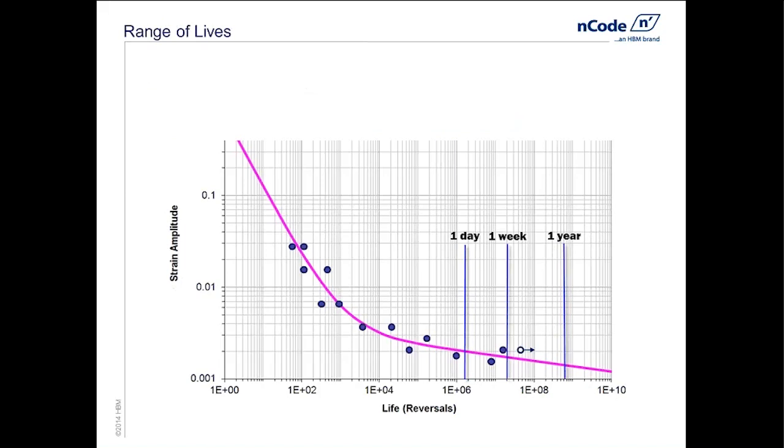Here we're looking at just kind of an arbitrary strain life curve, and we're fitting through data. The blue dots here are all data points. This one point out here, with the circle and the arrow, is a designation of a runout. This is a test that we stopped at about 20 million cycles. That test was terminated, and that data point isn't used in the determination of the strain life curve at all. Now, one thing we want to identify is the valid range of data.